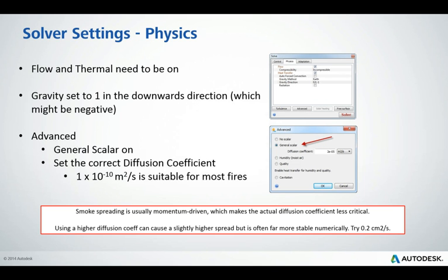We also need to set a diffusion coefficient, and because we're running a scalar analysis, CFD essentially is looking at how 2 fluids that are very similar diffuse together. Our recommended diffusion coefficient, which is given there, is optimized really for smoke within air. What we found is that sometimes that can cause a little bit of solver instability.